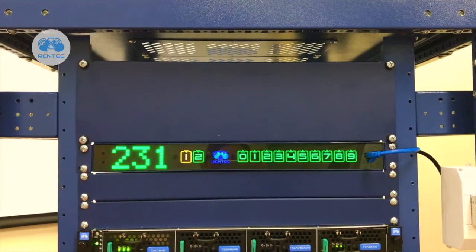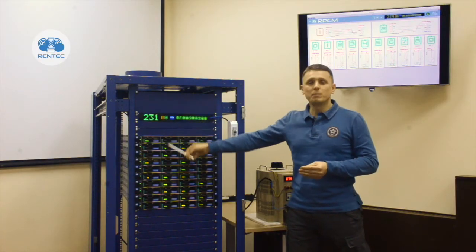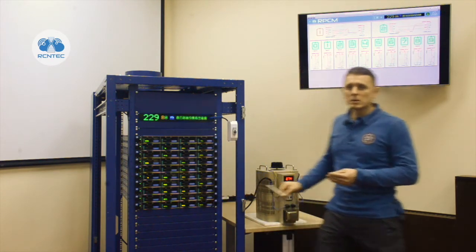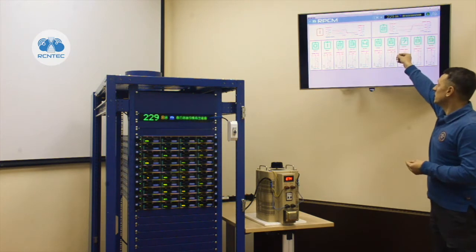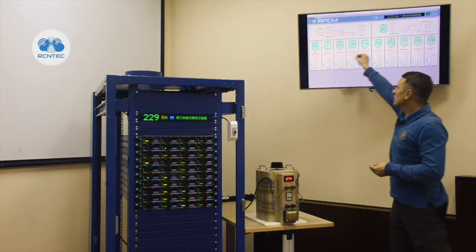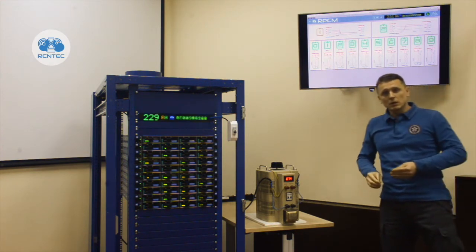As you may see, the ATS snapped into action. A switchover to the second inlet occurred without turning off the power supply of the consumers. We can see the same thing in the RPCM Web Management Console, where the second inlet became active and the first inlet is now in a mode where the qualitative characteristics have exceeded the defined limits.